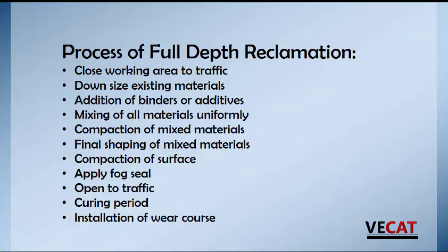Finally, after the final shaping, we're going to compact anything that was loosened during that, apply a fog seal, and then open it to traffic. Very important here, some of these materials we're going to use have a curing period. So cement, for example, we generally want to stay off of a cement-treated base for at least 3 or 4 days. Emulsions are typically somewhere around 3 days. Foamed asphalt is probably the only exception that we're trying to get on it as quickly as possible. And then finally, we have the installation of a wearing course.